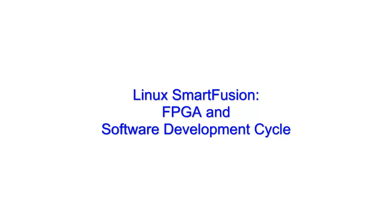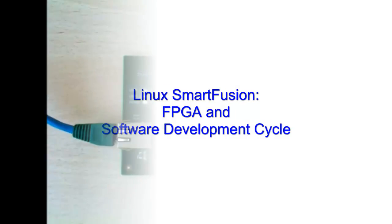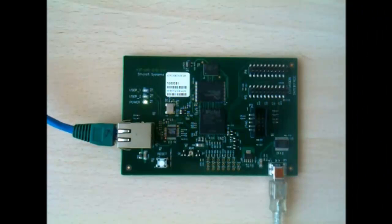This video illustrates a possible FPGA and software development cycle in Linux for the Microsemi SmartFusion device. This demo runs on the MCraft A2F LNX EVB board included in the Linux SmartFusion evaluation kit. The main concept is that Linux running on SmartFusion NFS mounts a directory on a development host, making host files and directories immediately visible to the target.